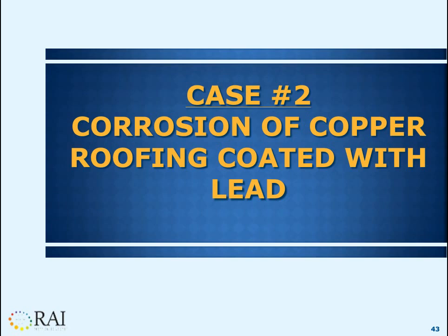Lead-coated copper is occasionally used on buildings in the United States because the lead gives a dull gray, antique look that is desired by some, and the lead should last decades. The lead is usually applied to copper sheet because lead is not very strong as a standalone material, and the copper substrate gives structural strength as needed, particularly for roofing.